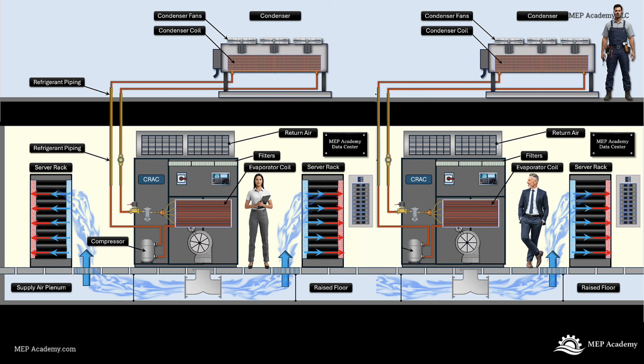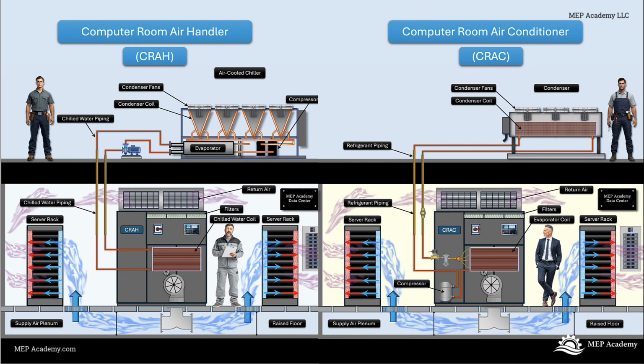They do not require cooling towers. They do not require condenser water pumps. They use little or no water for heat rejection, and they avoid many of the water treatment requirements associated with cooling towers. This makes air-cooled systems attractive in areas where water is expensive, limited, or heavily regulated.